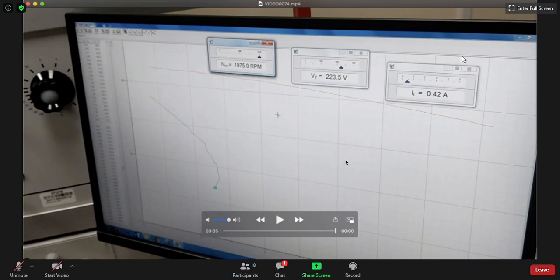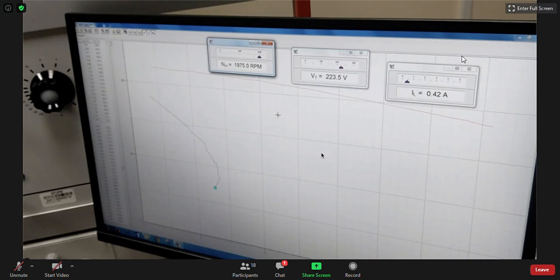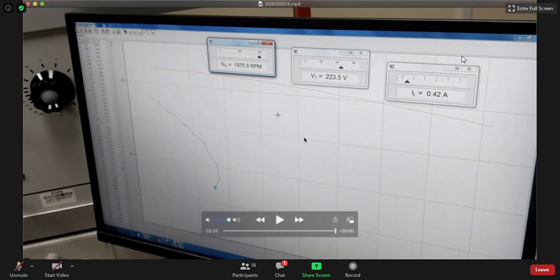So now you can understand that in your oral test or final exam, we normally ask a question about these characteristics, because you are watching these characteristics. We can see which one is sharper, so you can immediately understand that the shunt generator's slope is sharper than the cumulative compound. It means the cumulative compound is above the shunt generator characteristic.